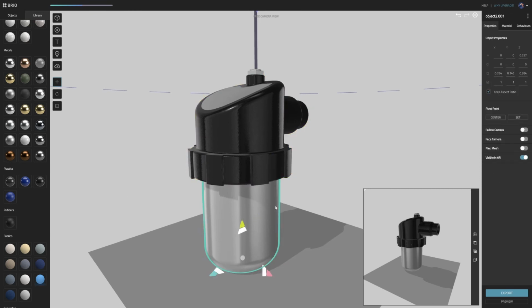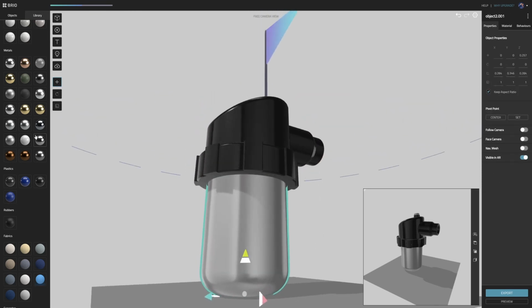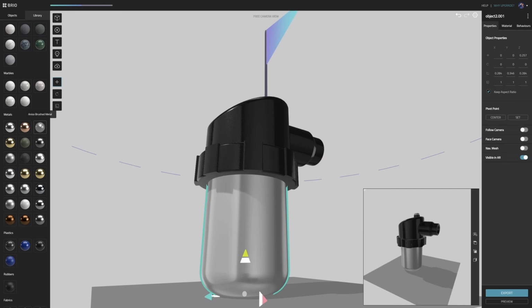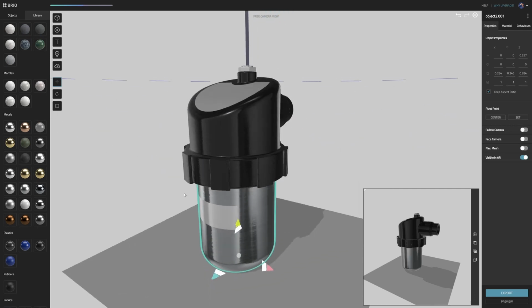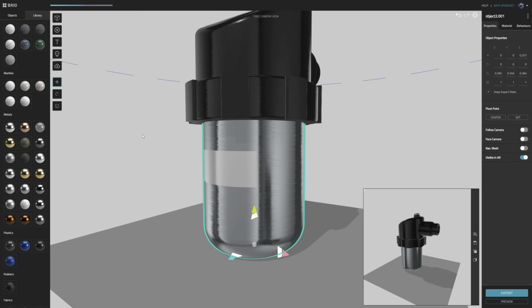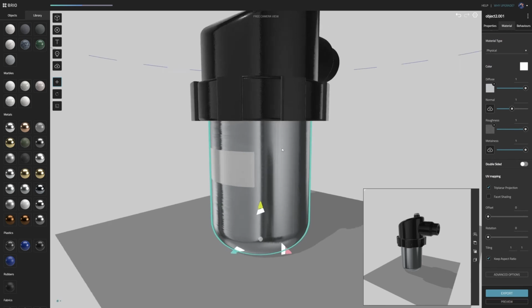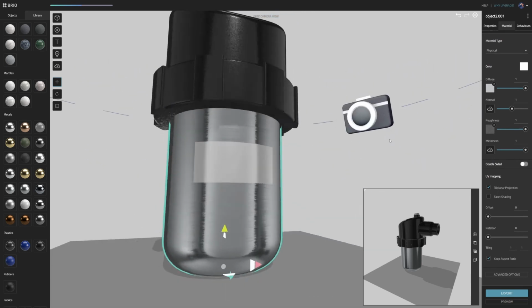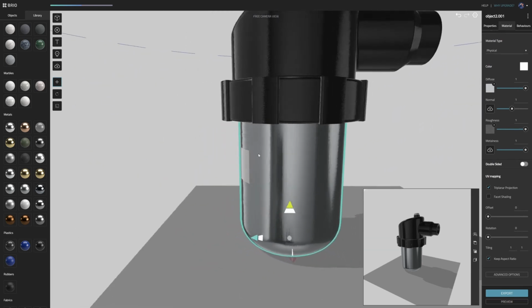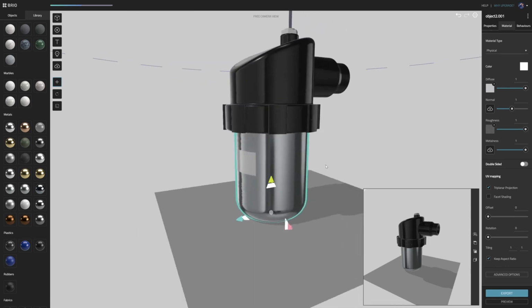If we select the bottom cylinder object, we're going to assign this anisotropic brushed material, and with that active, we can go in and change the mode to triplanar to get a decent look in this case, and have all the brush direction going in the right way.